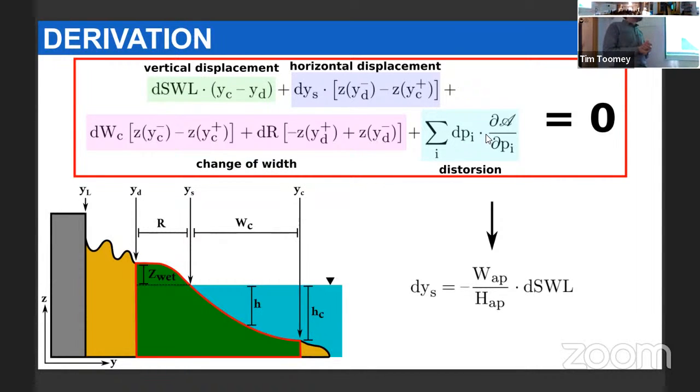There are different parameterizations for that, and then usually it's computed as a fraction or a function of the depth. Depending on the incoming waves, usually most of all their height, and sometimes also their period, you could compute this instantaneous critical stress that you need to start sediment mobilization, and then compute this depth here. Once you know this depth, since you know the shape of the profile because it's defined by your parameters, you could also know this width here.